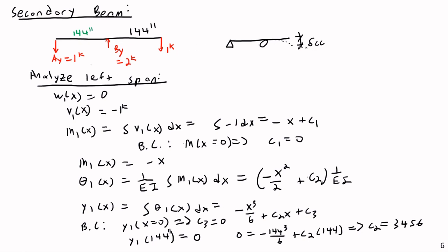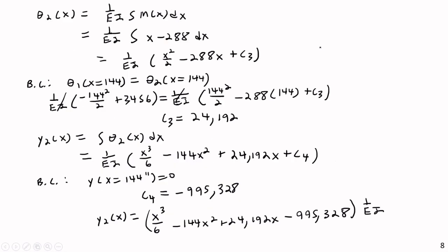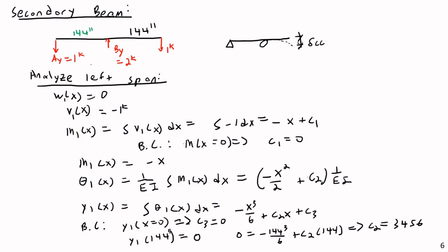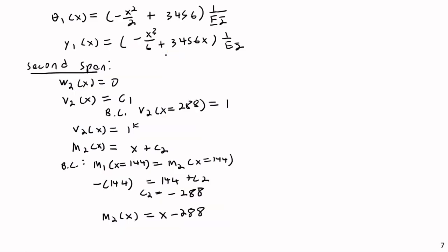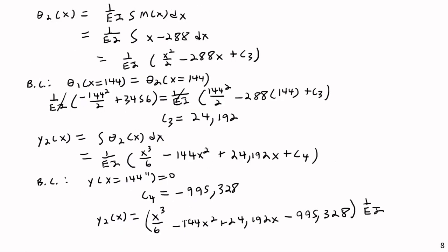The deflection at joint C under a unit load applied at C. Because I have only one redundant, I'm not going to have a BC and a CB and a BB. If you only have one redundant, you just have a single delta, just like we've looked at before. So now that I have the full deflection functions, finding delta CC is very easy. All I have to do is plug in x equals 288 inches into the equation that I've already calculated. So once I have this, I now have the entire thing, and the rest is just plugging and chugging.